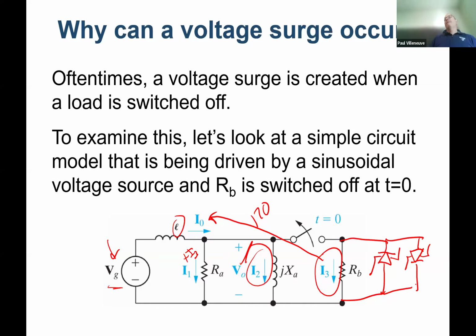But actually, I think you would use what's called a metal oxide varistor that protects in both directions. Once the voltage goes above its threshold, where it starts to conduct in the reverse bias region, it will not do anything until it starts to conduct. So the surge suppressors in your house are definitely not a capacitor. It's just a device like this. Well, that's even simpler than I thought it would be. Yep, all it is is some semiconductor material. It's kind of like how an LM317 voltage regulator works, right? Once you get above about 15 or 17 volts, they start to conduct. Those are a little more sophisticated than that, but this is just for high surge suppression.